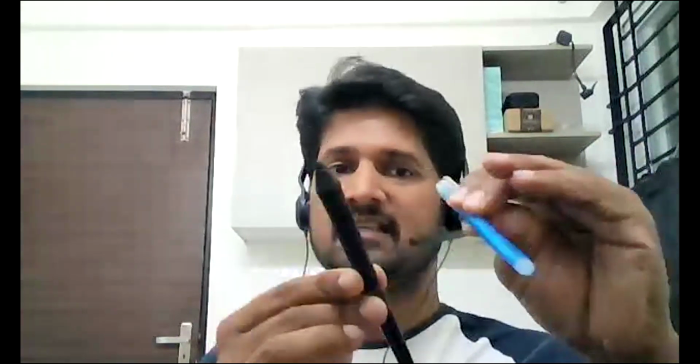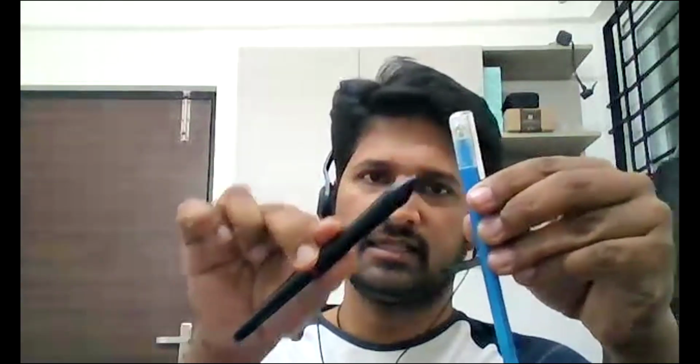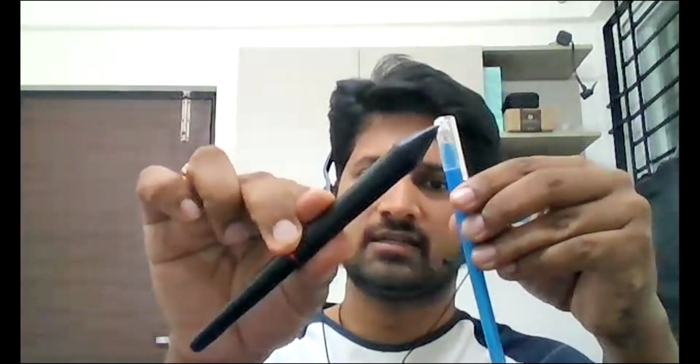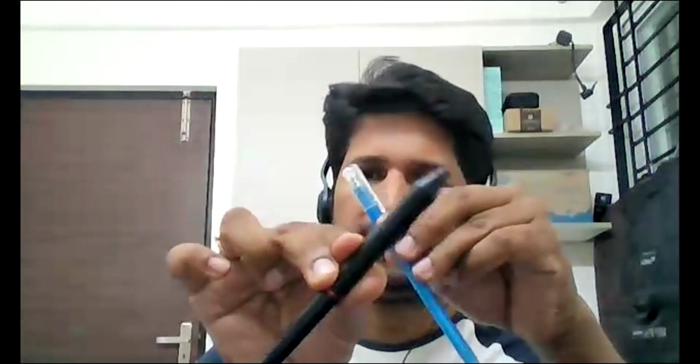Fine. In such cases, the force can produce torque about the axis. It should not be parallel to the axis. It should not be intersecting the axis. Its line of action should be away from the axis. In that case, the force can produce a torque about that axis. And how you calculate the torque, we already saw. You take any one point on the axis, do R cross F, and then take its component along that axis.